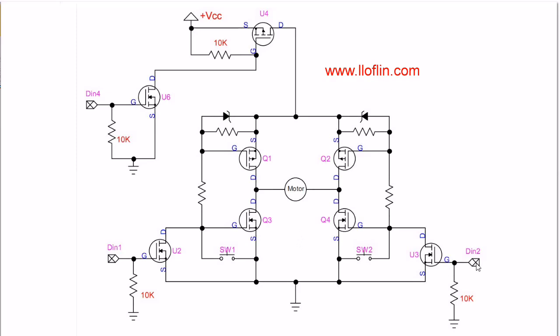In this case down here, a high in here, it will do the same thing as pressing SW2. A high here, low there. This transistor turns off. This transistor turns on. This one is still on, assuming that's low, and creates a path from Q2, motor, Q3 to ground. Same thing over here, a high input, low over here. Creates a low there, turns off Q3, turns on Q1, Q4 should still be on, Q1, motor, Q4, ground.